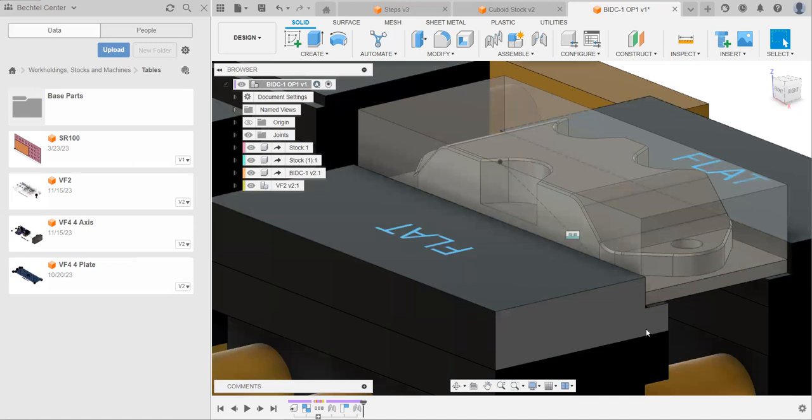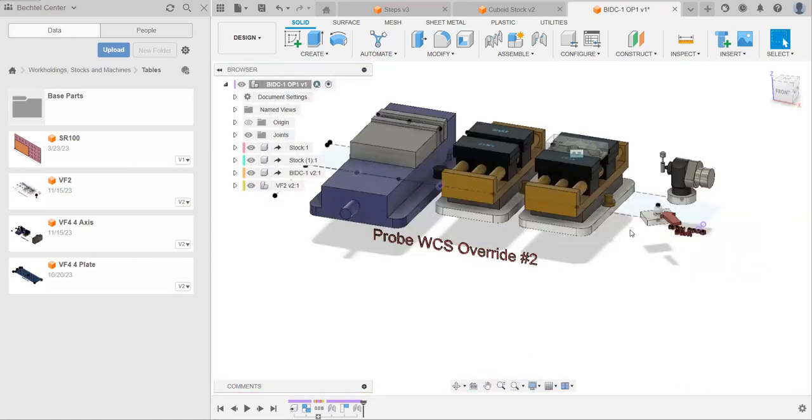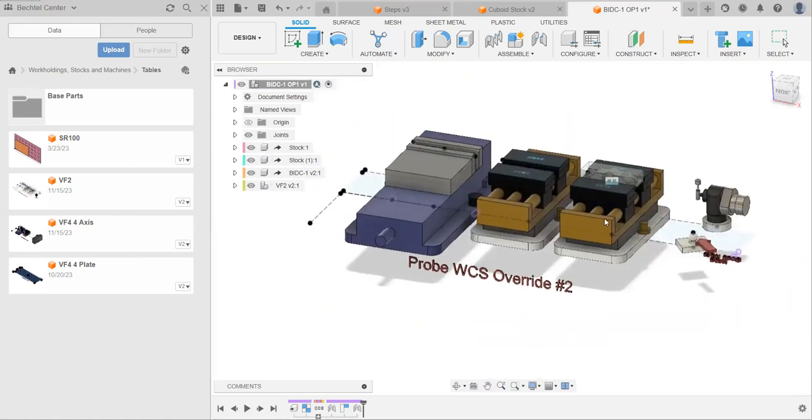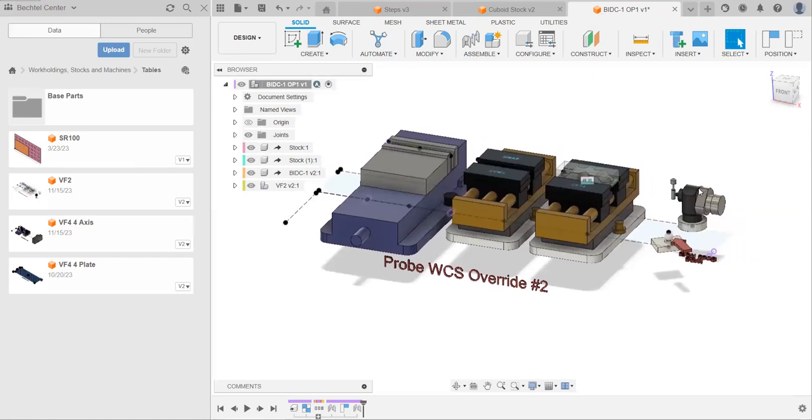Now that that's done, we need to joint our vise to the origin of our model. And the reason for that is that we can still just kind of drag our whole vise around like this. And the reason that's not good is because if we're making CAM and it's going to say, hey, tool should go here and then here and then here. Well, if it tells the tool to touch this little probe up here, and then we move this whole thing a little bit to the right or to the left, then all of a sudden it used to be touching here, but now it says, hey, I need to regenerate. I need to go and figure out where all the models are again. And that's just going to spend a lot of time generating and regenerating all your stuff if you even bump your model. And that's not great.